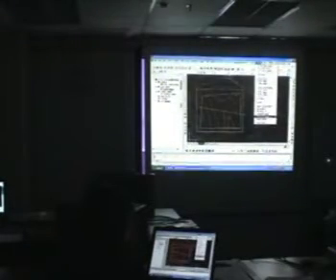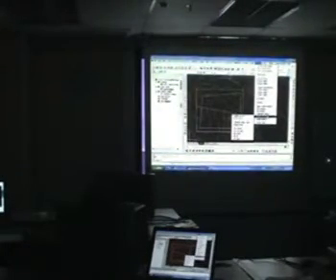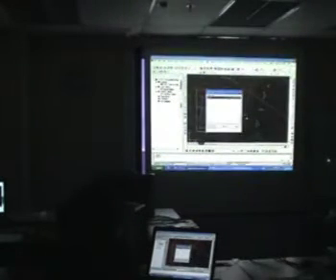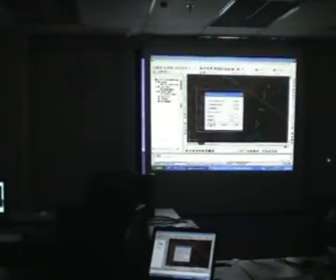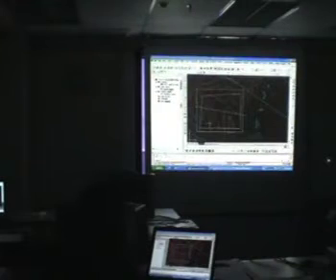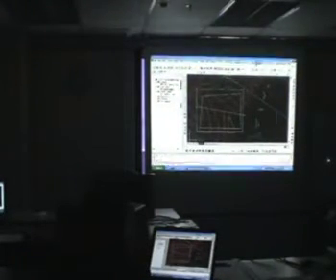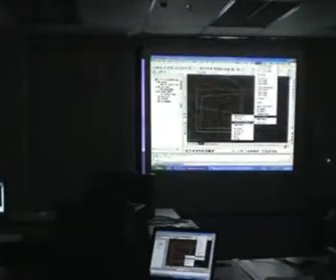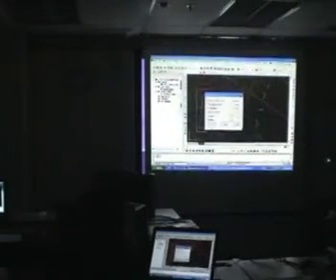The third method, using the section volumes, is a bit different because we can't run the volume calculation straight away. We need to sample some sections first. So this is what I'm going to do. I'm going to sample some sections. Just hit OK. It's sampling sections across my original and the proposed level. And now we run our calculations. Just click calculate volume total and select the site. As you can see, within the section volume method there are two further methods. One is the average end area method, and the other is the prismoidal method. These two fall under the section volume method.